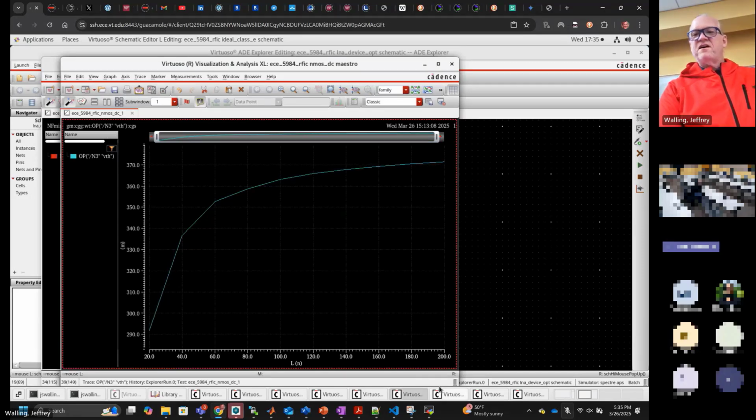Okay, so the question came up the other day, or I mentioned, what happens as you increase the length to the threshold voltage. I got a question about why this happens. Why does the threshold voltage increase? And then I decided, well, let's go plot this, because fundamentally it's a second order reason that threshold voltage decreases as a function of increasing length.